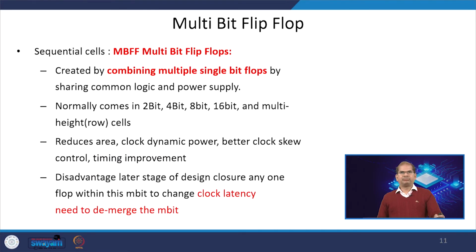There is a concept called multi-bit flip-flop. It is created by combining multiple single bit flip-flops. If multiple flip-flops are sharing a common logic and power supply, we can replace those flip-flops with a multi-bit flip-flop. It comes in different flavors like 2 bit, 4 bit, 8 bit, 16 bit and so on.